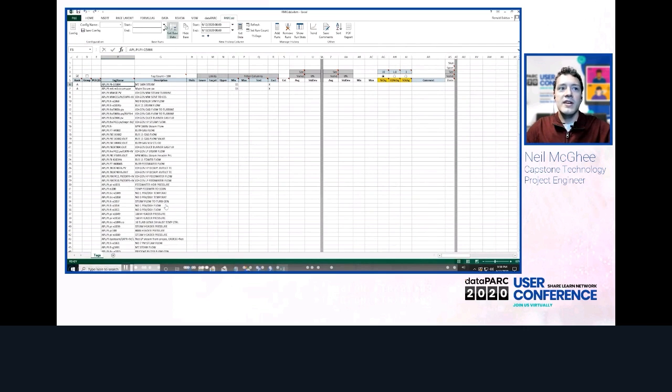Next, we select a start and end time for our baseline period. We will choose last month to be the baseline so that we get a long enough period to get a good picture of the process. We then click the Get Base Data button to start calculating our average and standard deviation for this base run. This calculation goes pretty fast, but we'll still skip over it now for the sake of time.